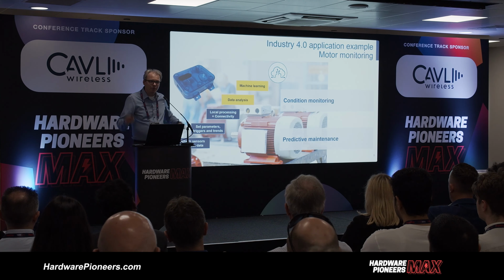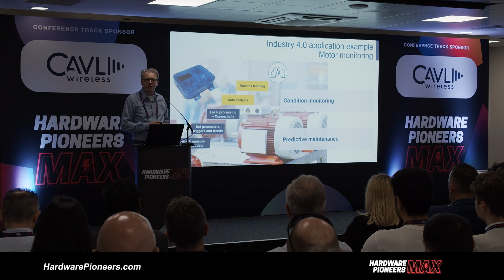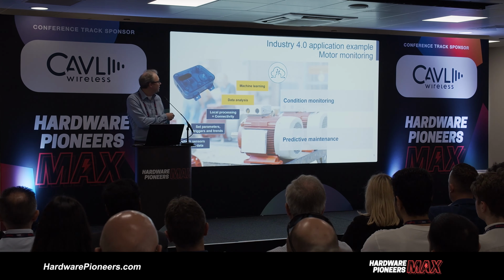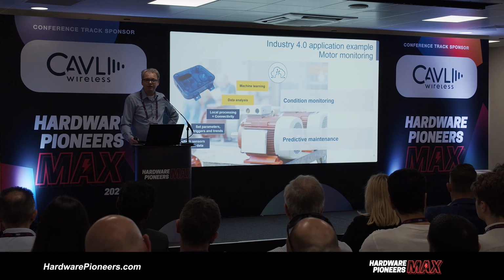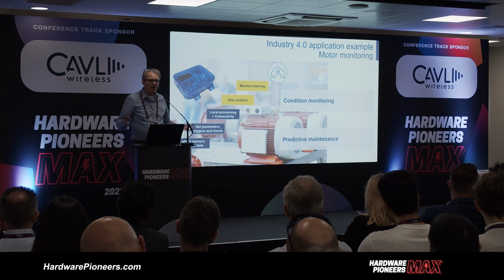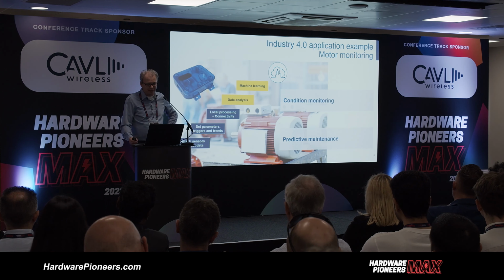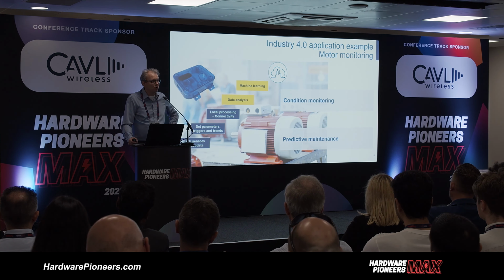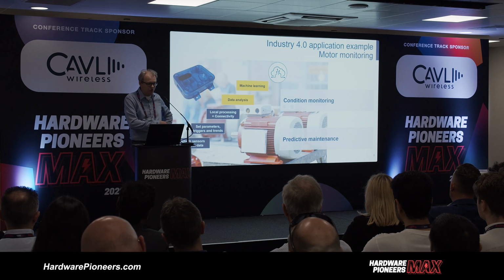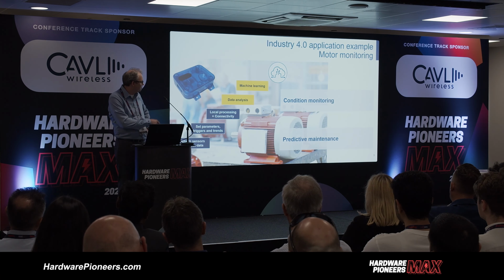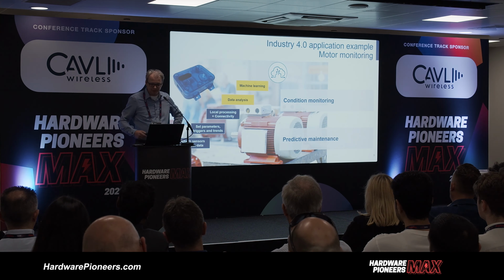Now lately, when we are getting more and more processing power in the main hosts, this kind of local processing and connectivity, for example to the cloud, is very easy nowadays. And this is, in a way, helping to boom this type of application. And then the next step is really to do more and more data analysis and then different kinds of machine learning. And from this, we can then go from condition monitoring to real predictive maintenance.